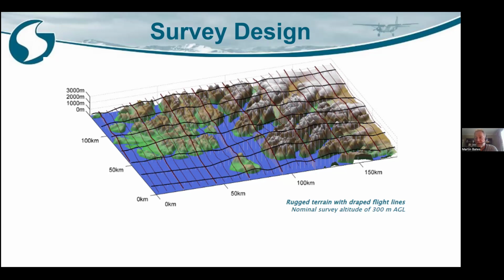Sometimes we'll hear about mag storms. Well, they happen. That's extreme magnetic change, and that can be too high for us to correct for, so we can't fly at those sorts of times. But it's happening at a lower level all the time. There's no time when the magnetic field is not changing. It's always being perturbed, and we have to monitor that and remove it.